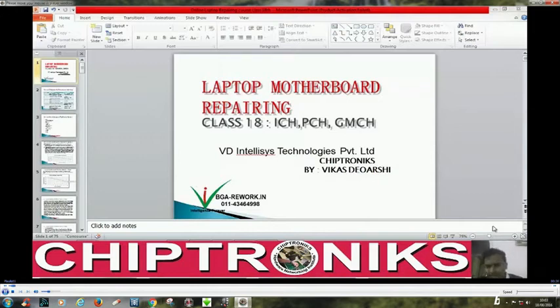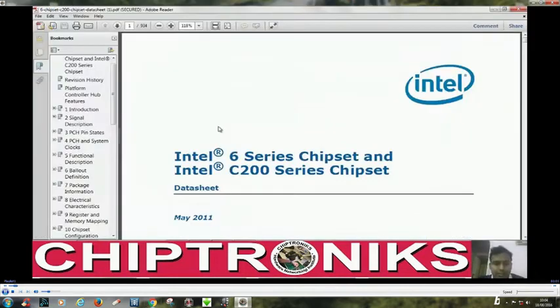And as I have already discussed in my previous class, for analyzing any kind of board, what you have to do is see the kind of Intel chipset that is present in the board, right? So if the board is an Intel Series 6 chipset kind of board, then we have to download the Intel data sheet, that is, the Intel Series 6 chipset. And if your board has something like HM55 or HM57, then that is an Intel Series 5 chipset.